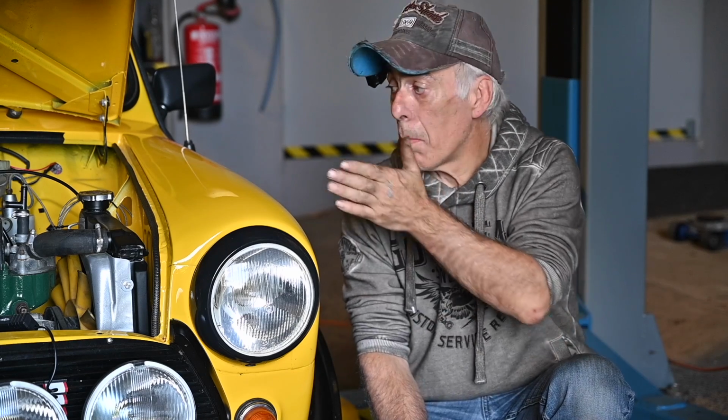So what I just showed you was a little bit loud, so maybe you could not hear what I was saying, but I've been revving up the engine to different RPMs, 2,000 and 3,000 RPM, and then I used my flashlight and I adjusted my retard knob until my marker on my pulley lined up with the pointer of top dead center on my distributor cover. And by doing so, I could then read the actual amount of degrees that I had to set to line that up.